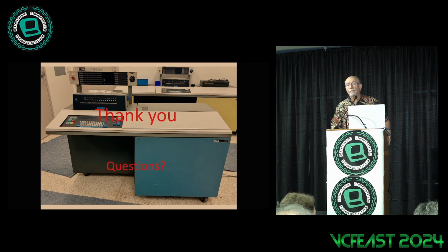One advantage that Schottky logic had, that only Schottky, not low power or fast, is if the inputs changed at the same time as the clock, both Q and Q bar outputs would go low, and you could detect that and then use that to condition your... Right, with some more safety logic around it. Was any of that sort of thinking in the IBM?